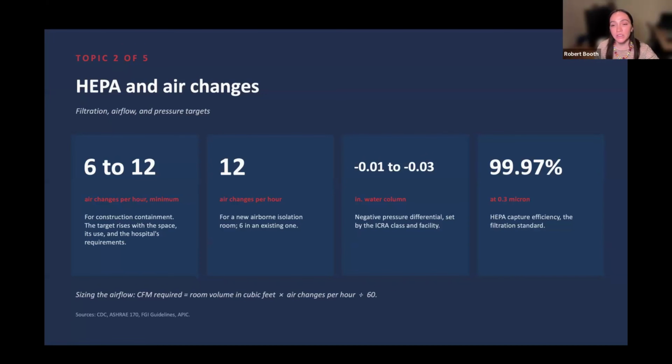Let's talk a bit about actually disposing of those HEPA filters when they're loaded up. Some of these projects, you may be pulling in mold, possibly. When you're pulling out a HEPA filter that's loaded with all of this debris and possibly contaminants, how do you dispose of that properly? Well, we want to follow good industrial practices, and there's a process called bag in and bag out that we use in a hospital for isolation risk, because we don't want our facilities management engineers and HVAC folks to get exposed to some of the contaminants that could be in a filter.